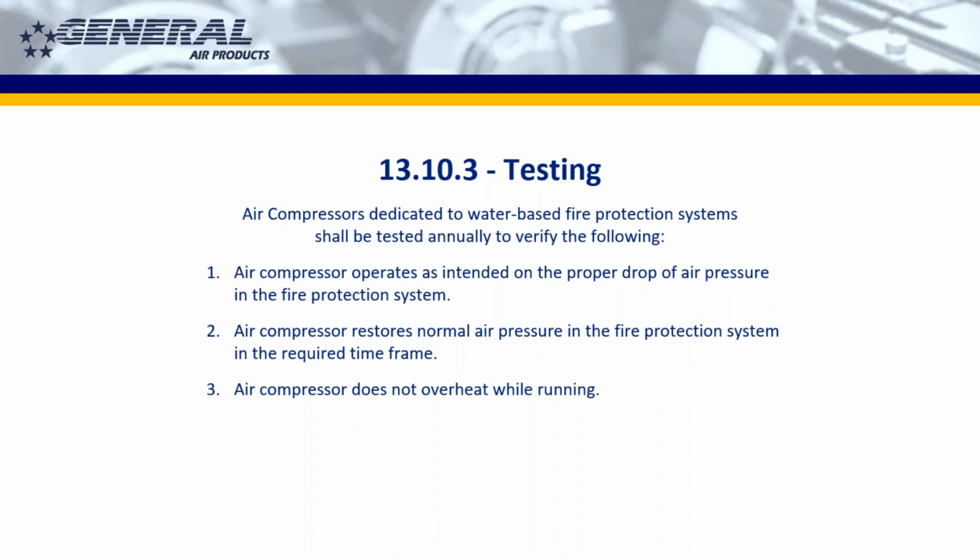Just so you know, compressors do get hot, to the point where you don't want to touch them, especially after a 30-minute run. The motor's going to get hot. The air coming out of a pump is anywhere from 200 to 400 degrees. So it gets hot, so be careful with that. But it's up to you to determine, is it overheated or is it just running hot? It's supposed to run hot.